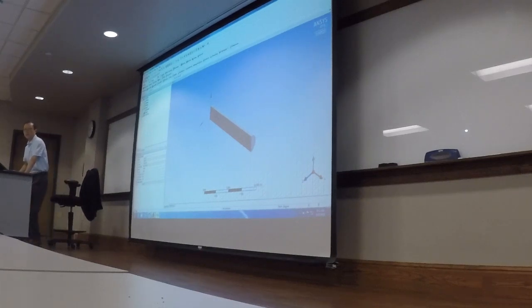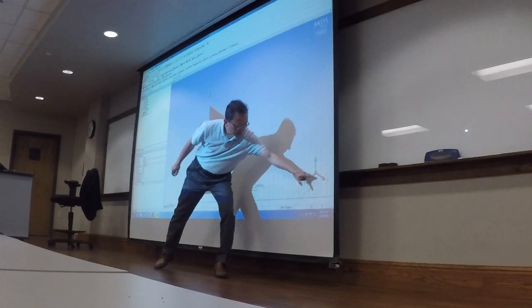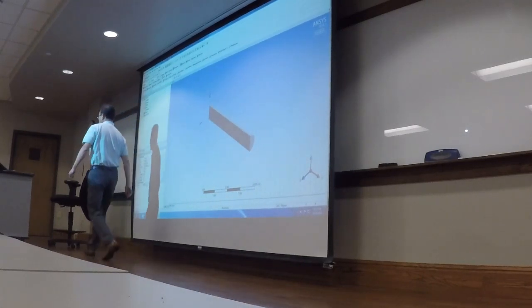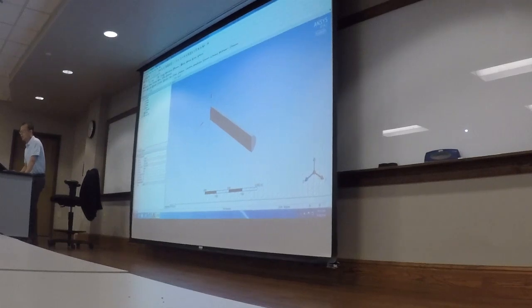Okay, the next, let's create the branch portion. The branch portion is on the ZX plane. But this time, we don't need a new plane. Let's just go to New Sketch. So first click on ZX plane. New Sketch.